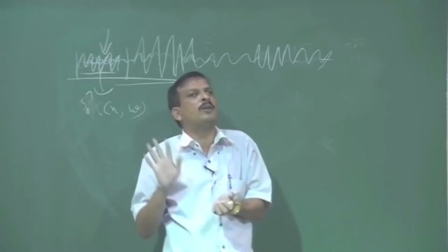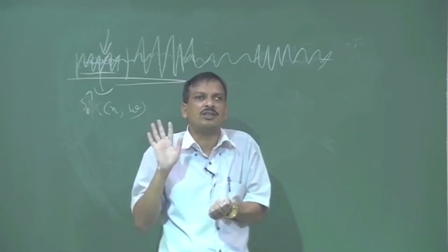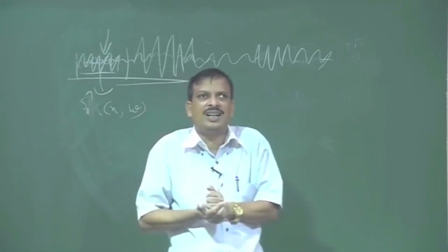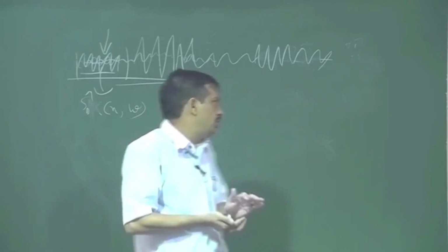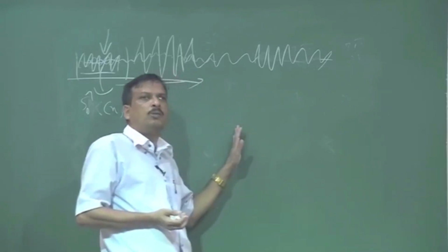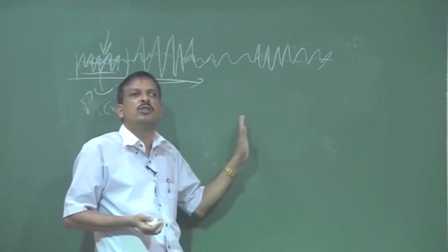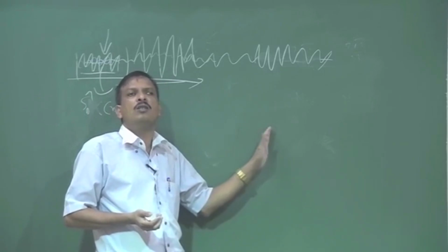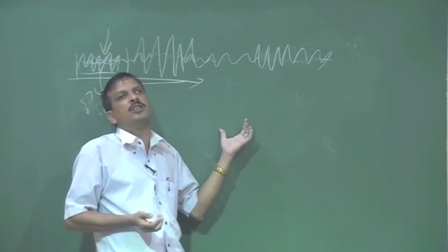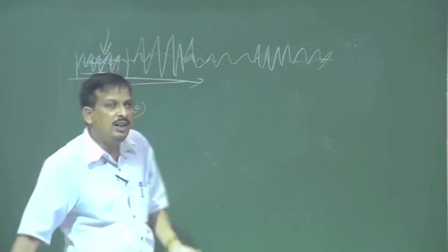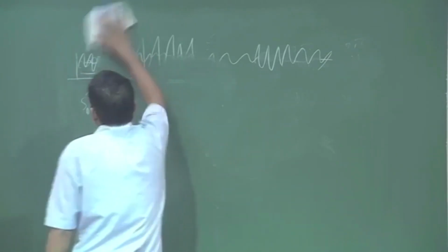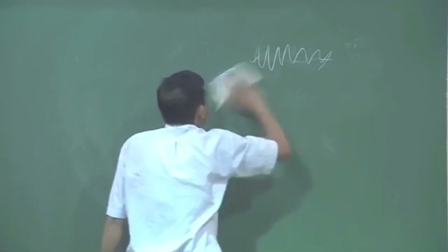You can write an OLA algorithm to reconstruct the signal, because I have to get back the signal again. Reconstruction is only possible if I suitably choose the window and also the shifting of the window. So that is why, in any parameter extraction, we do the frequency analysis of the speech signal.